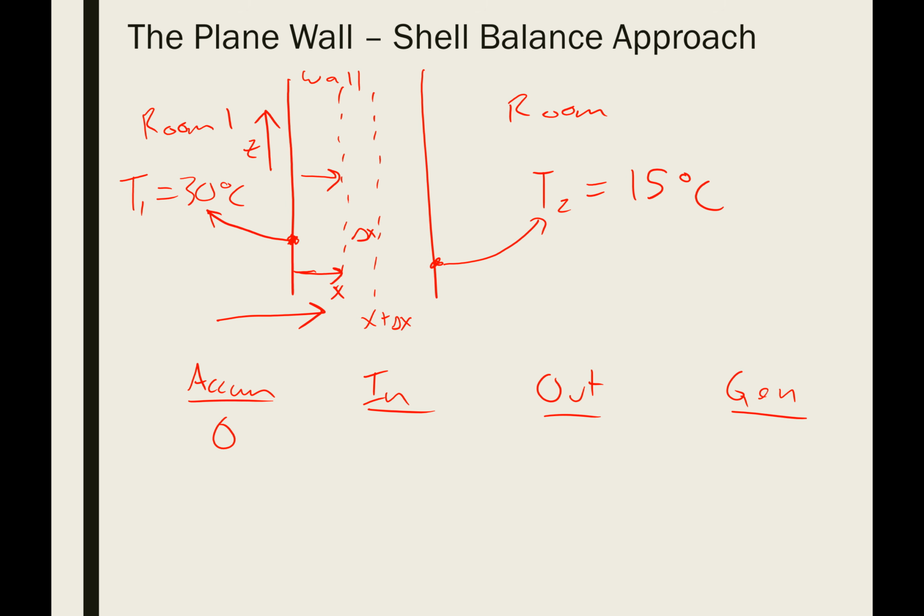It would not be thermal equilibrium. Thermal equilibrium would mean that everything is at a uniform temperature, so you have no flow of heat. Steady state is an important mental distinction to make, because steady state means something different than equilibrium. Sometimes they're the same, like if we set both rooms to 30 degrees and then waited, they would reach a steady state where everything, including the wall, is just at 30 degrees.